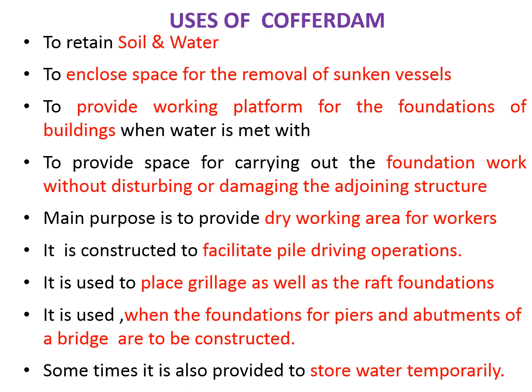So what are the uses of cofferdam? There are many uses of cofferdam, and the list of all these options is given here. First, to retain the soil and water, this is the first important use. Next is to enclose the space for the removal of sunken vessels. Sometimes some vessels sink in a river or ocean, and if you want to take them out, then you have to construct the box all around that, dewater, and you can take them out.